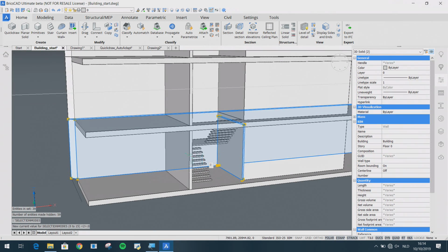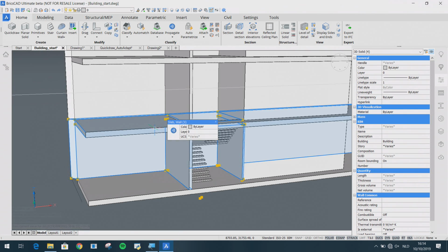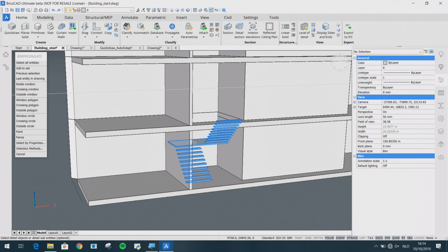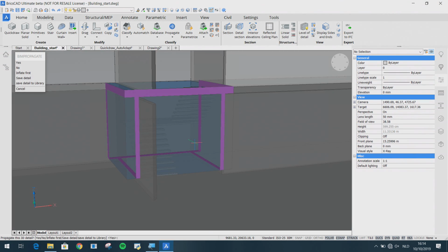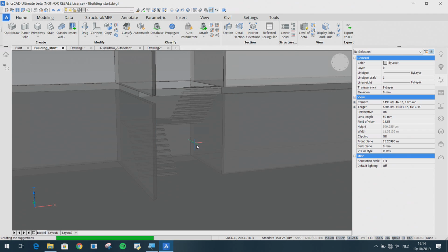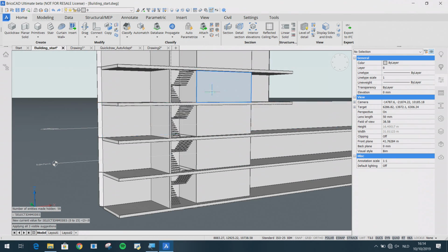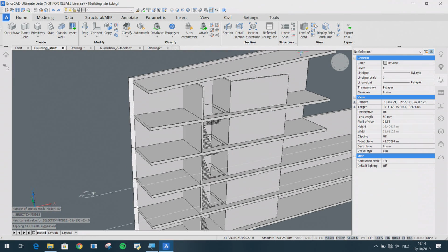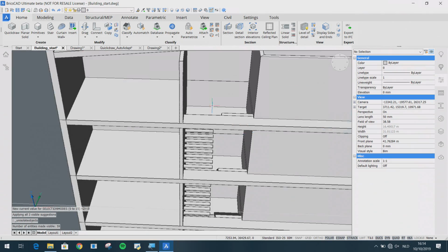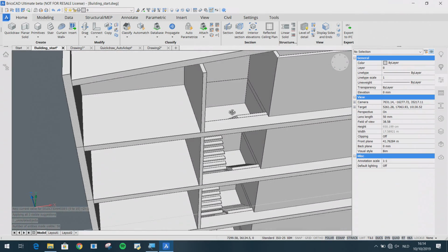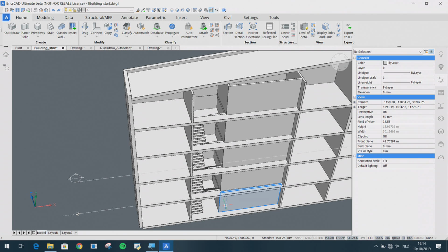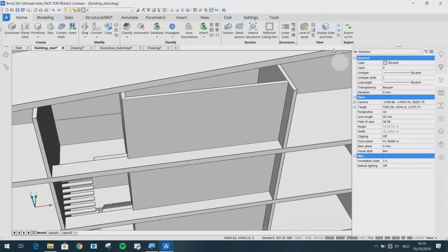He's selecting the walls surrounding the stair and the slab to which the stair is attached as base solids, a reference for the stair, and the stair then the detail, and then Propagate finds for him other locations where this exact stair configuration matches. And so, like this, it's very easy to have all the stairs in the building that we need right now. And also note, not only the stair is duplicated, but also the opening in the slab that is needed for the stair is replicated by Propagate.